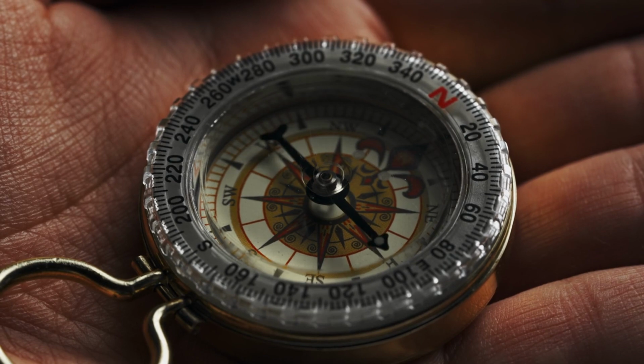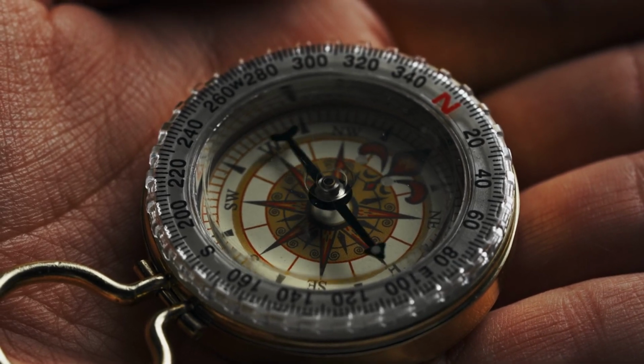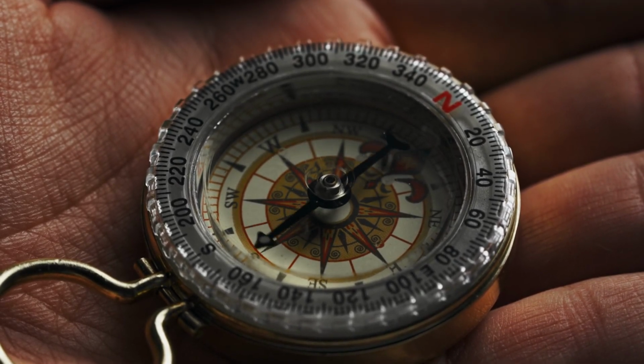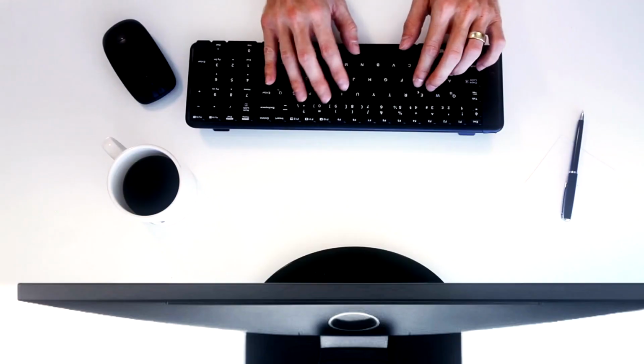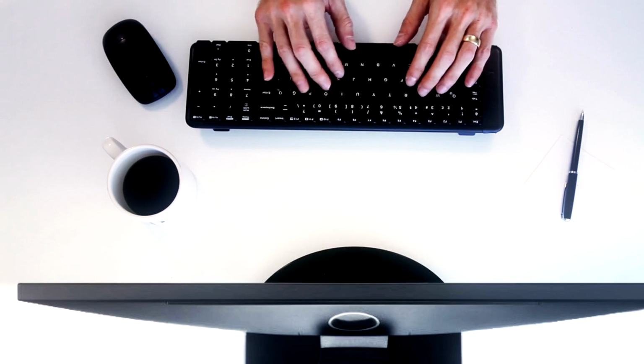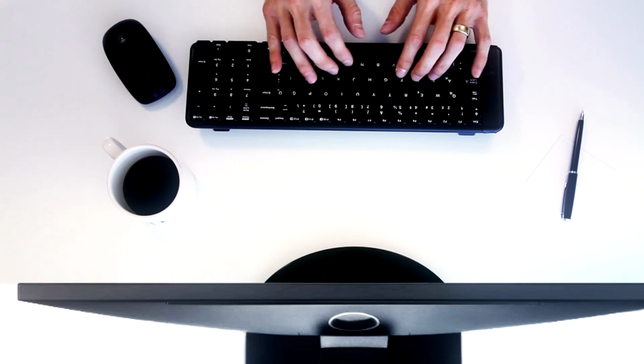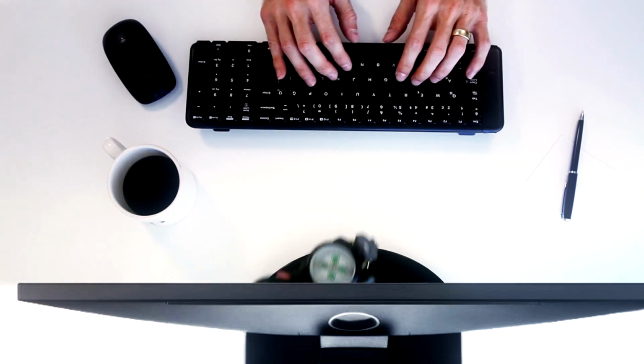2. Your true course is 302 degrees. Variation is 7 degrees W. Deviation is 5 degrees W. What is your compass course? 3. Your compass course is 250 degrees C. Deviation is 2 degrees W. Variation is 3 degrees E. What is the true course?